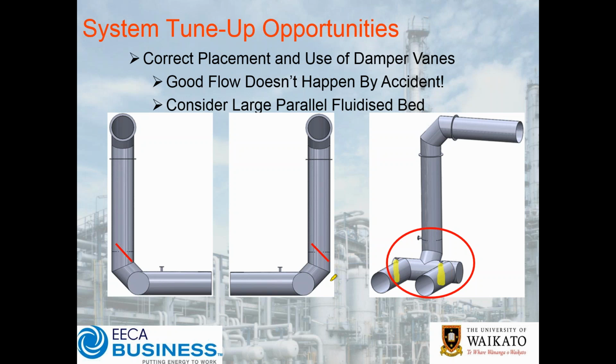Now what of course happened in the first instance, you'll notice that flow is trying to come down here and around the corner, and if we draw that on here, you can see we've immediately got a problem. This system was on a VSD. The VSD was left at 100% because they couldn't balance the airflow across the two sides. Why couldn't they balance the two airflows?